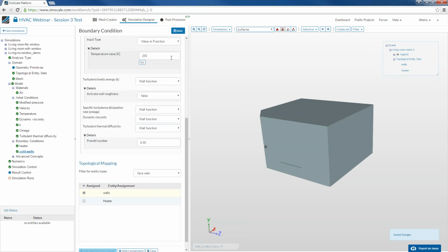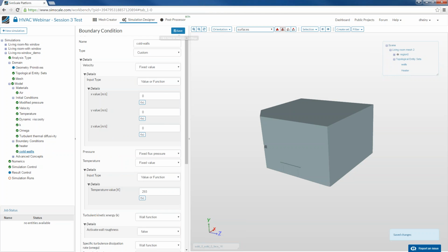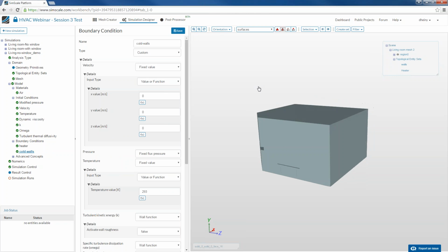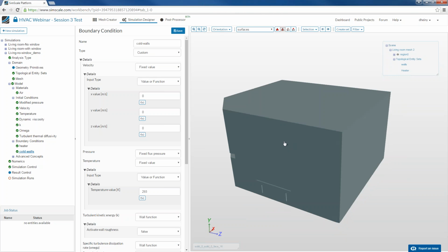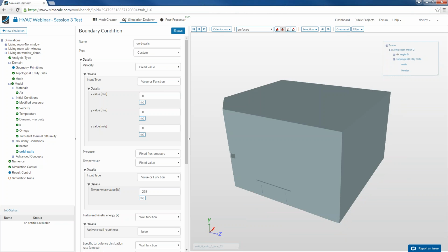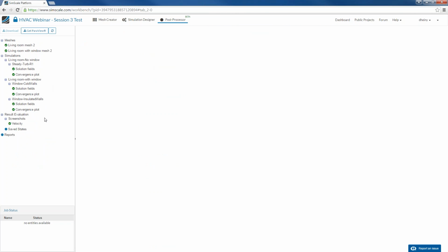There are some details that would now need to be done, but the engineering work essentially was just done. This was the important point, how we set up the boundary conditions, right? And in that case, we have only fixed temperatures. You could now go into different terms of heat fluxes, different adiabatic walls where the temperature is being developed, non-adiabatic walls, etc. So there would be all sorts of scenarios you can model through that. And this is the actual engineering work. This is why I wanted to make sure that I have it covered.